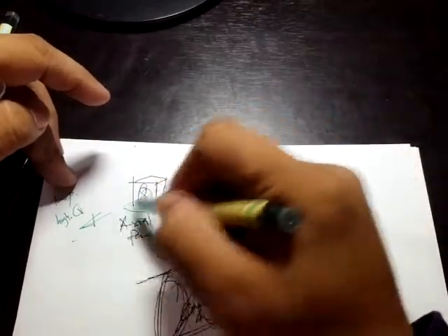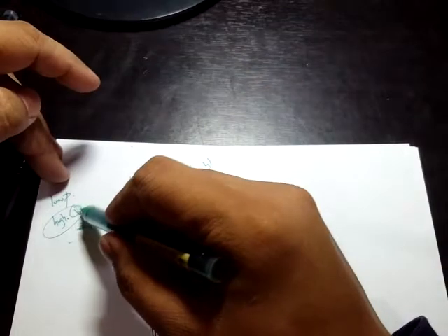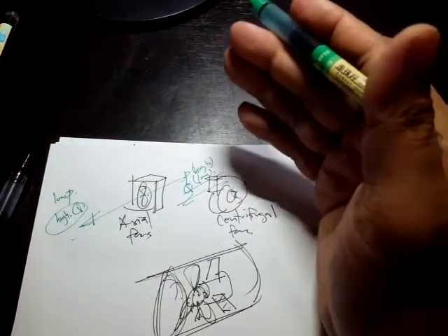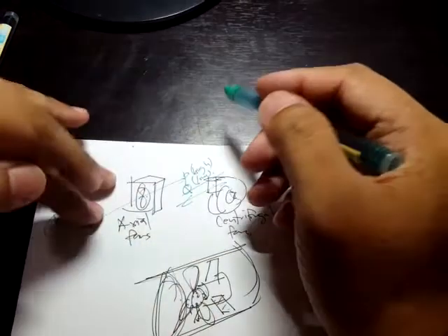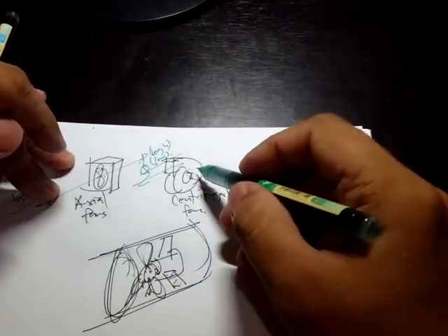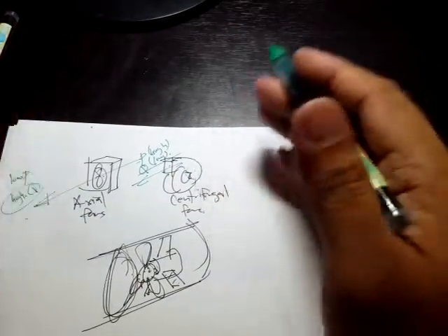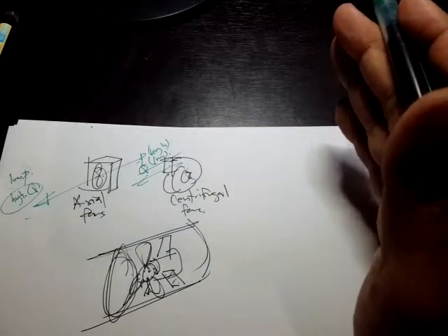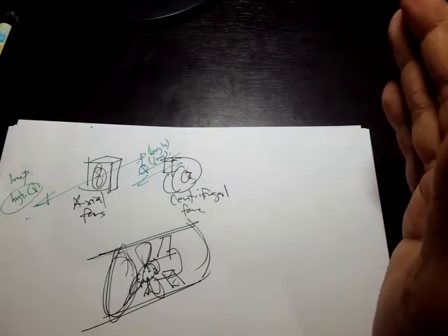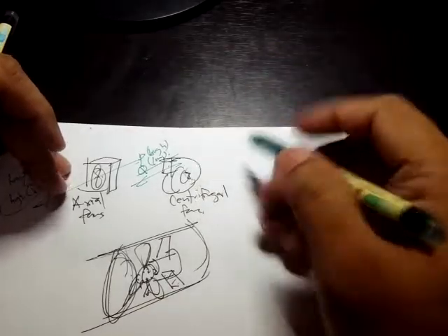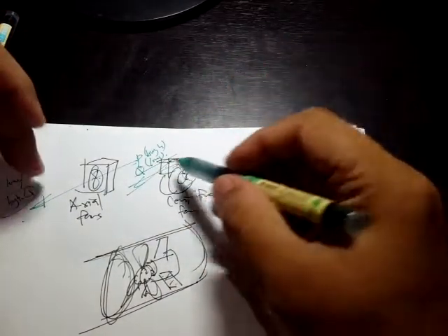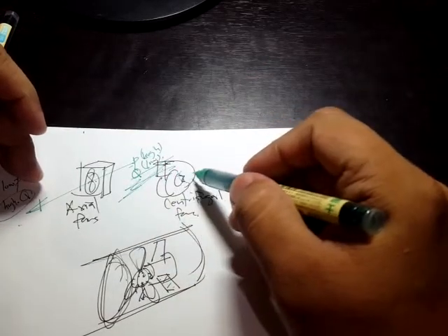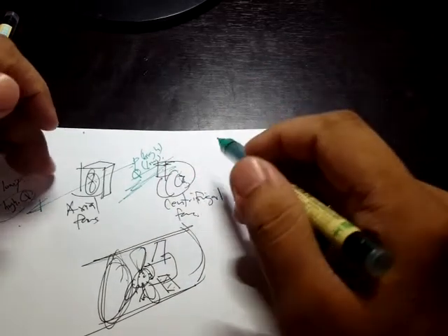So if we want more fresh air, then what we want is this. But of course, it has to be compatible with our required system pressure. But for example, if our ventilation system is in ducting systems wherein there are ducts, of course the pressure will be high, and what we may need would be these centrifugal fans.